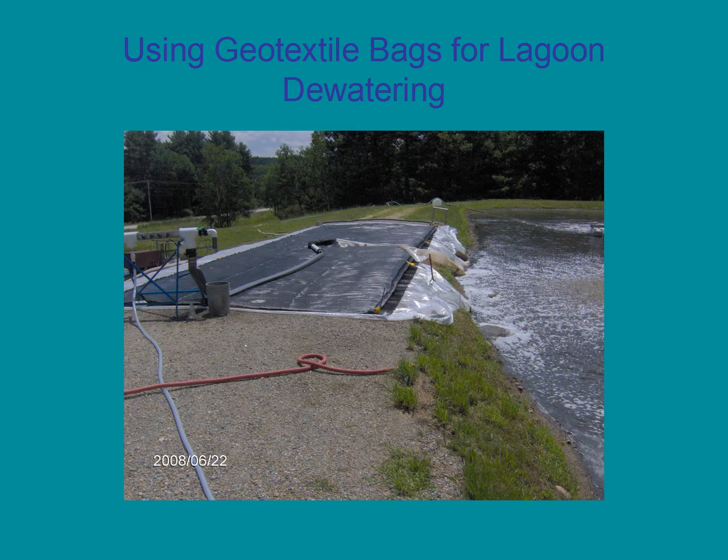Geotextile bags can be used to dewater wastewater lagoons. Sludge can be pumped from the lagoon with a dredge or a floating pumping raft. It can be pumped up to the bank and treated with a flocculant as it flows into the bag. Effluent flowing from the bag can be returned to the lagoon or diverted to another holding area.